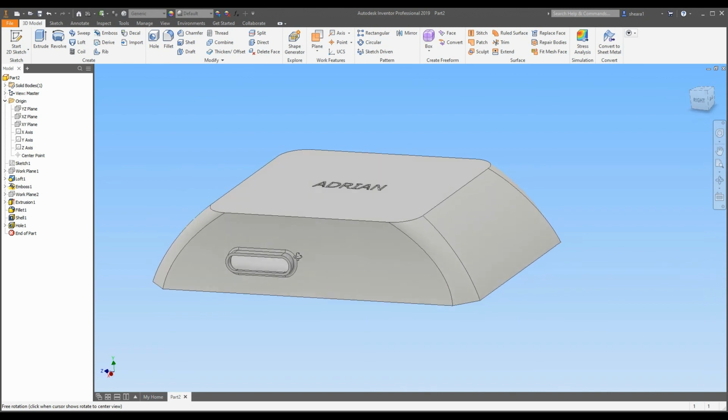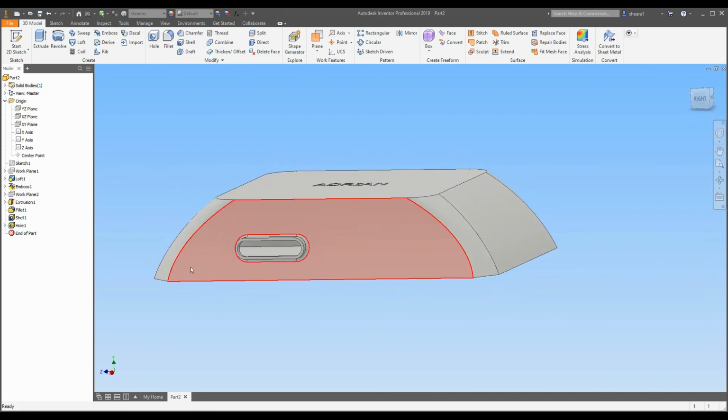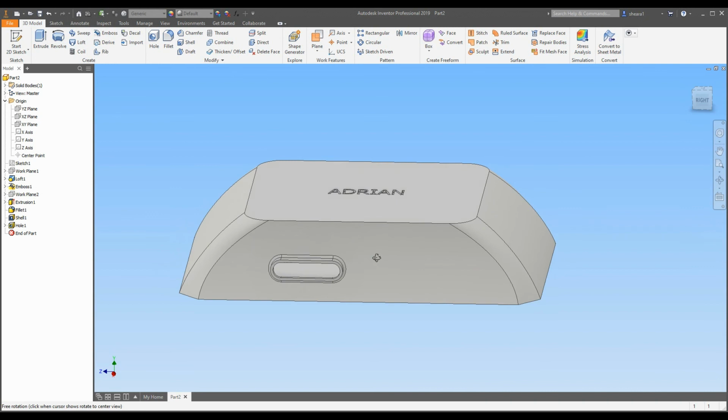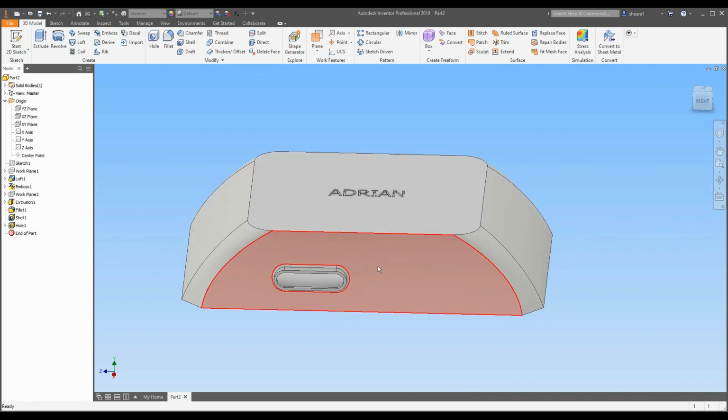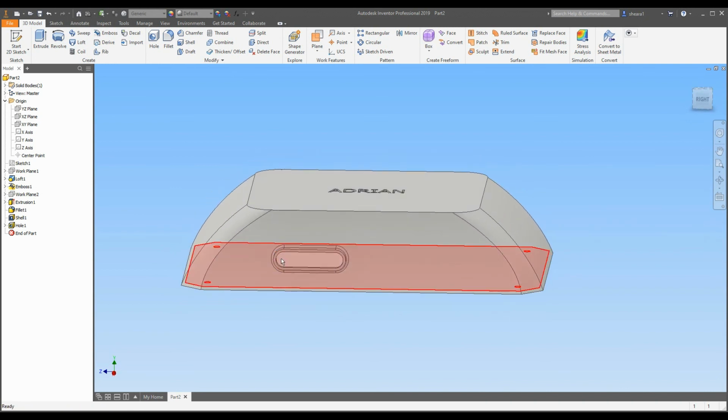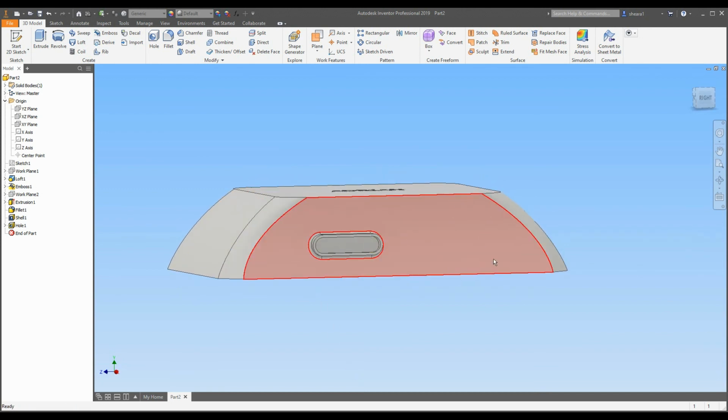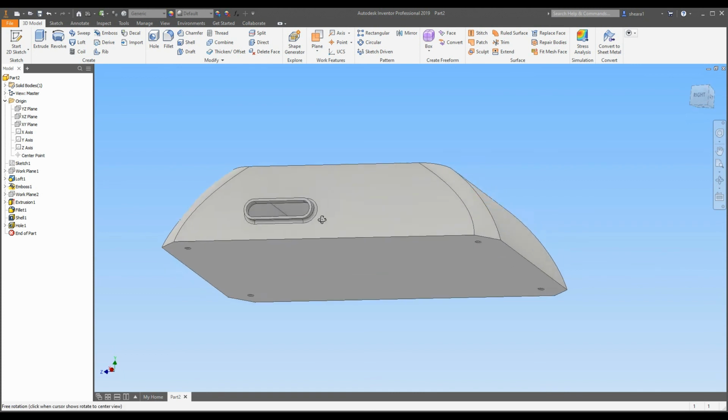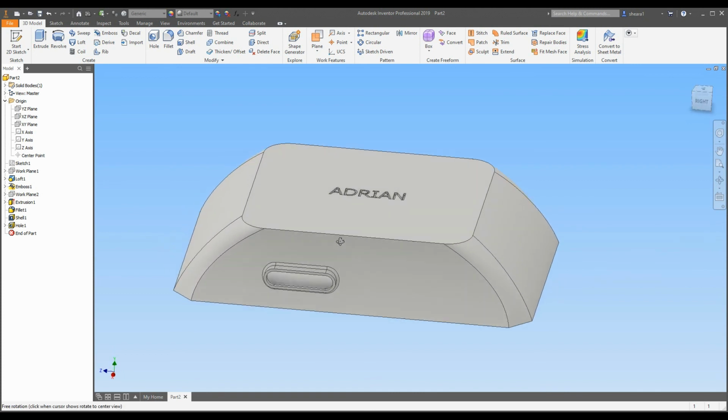If I could get a really expensive 3D printer, I could print this, but when it tries to print this top face here, it will have to fill this entire hollowed out portion with what's called support material that it builds up in order to actually build this model up here. And then it'll be nearly impossible to get the support material out. You'll have to put it in a corrosive bath, and it becomes a huge hassle.